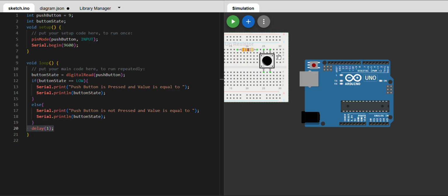So what I have done is, I have kept these two pins which have an internal connection between them, the push button to A, and you have to see this column number. This will be 30 column number, that will be 25. The next one will be 26, and the next one will be 27. And I have connected this particular push button upper pins to A25 and A26. Okay, like this you have to see the connection, whereas the bottom is to F25 to F27.